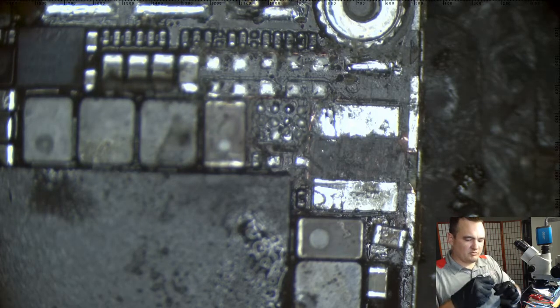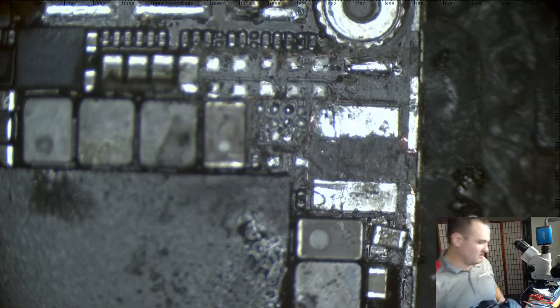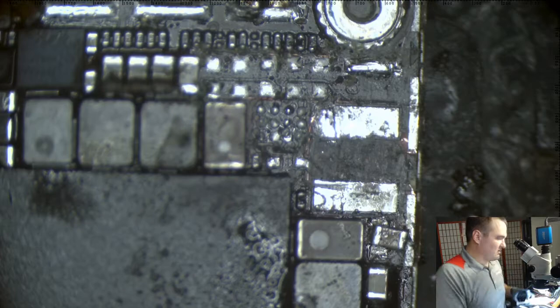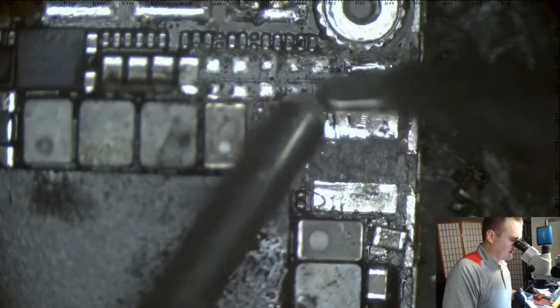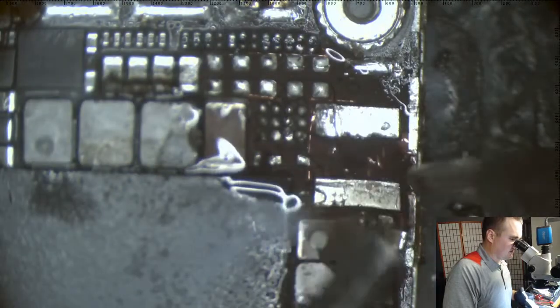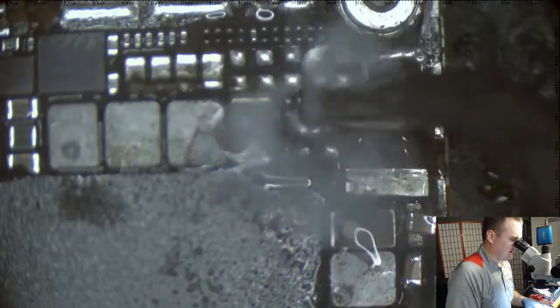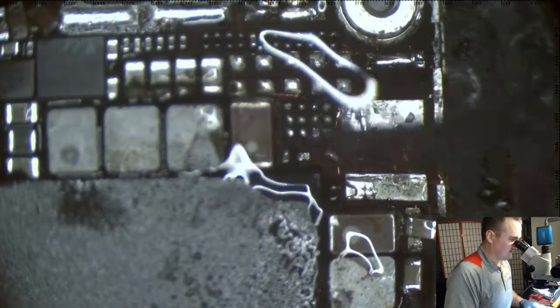You buy a reballed chip, you hope they put leaded solder on it, but they very well could have reballed it with the same RoHS high temperature unleaded solder as it was put on with at the factory. And in that case, you gotta use just as much heat to put it down as you did to take it up. And let's turn on the old cancer fan here.